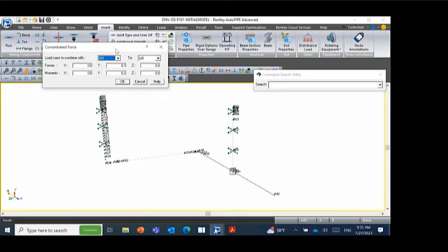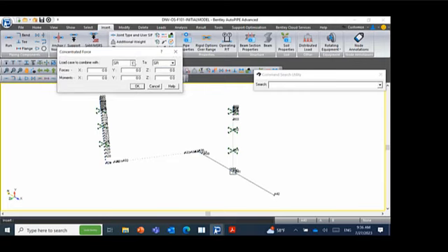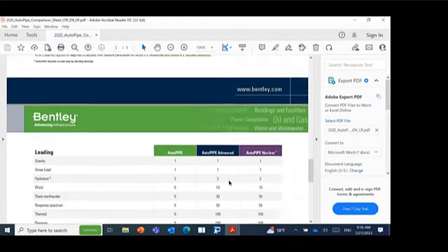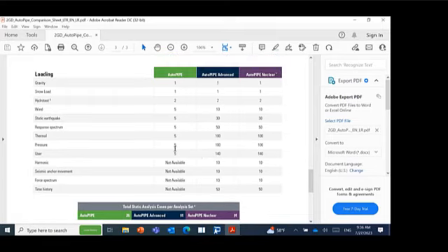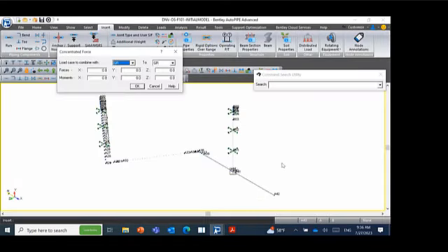Say, I want to put a force of 100 kilograms. Why? Because I consider that we have 100 kilograms, and this is related to a user case. A user case is an external case that has no name, and it's important to declare for some reason. How many do you have in AutoPIPE Advanced? Remember, user cases: AutoPIPE Basic 5, AutoPIPE Advanced 140. So that is important with user cases.